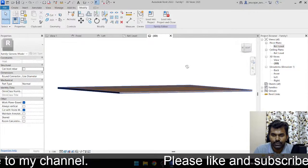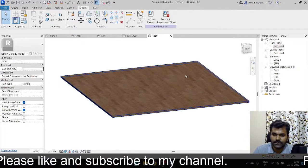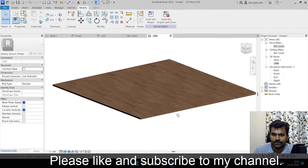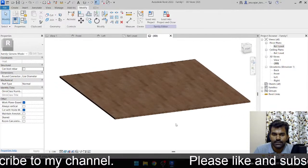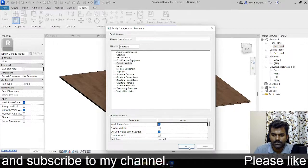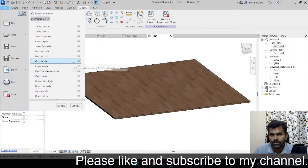In case you want to do your plywood vertical, then what would you do? Anyway, it's work plane based, so no problem. You can keep this as a single plywood. Then go here, the always vertical should be unchecked, work plane based, that's fine. Go to file and close.